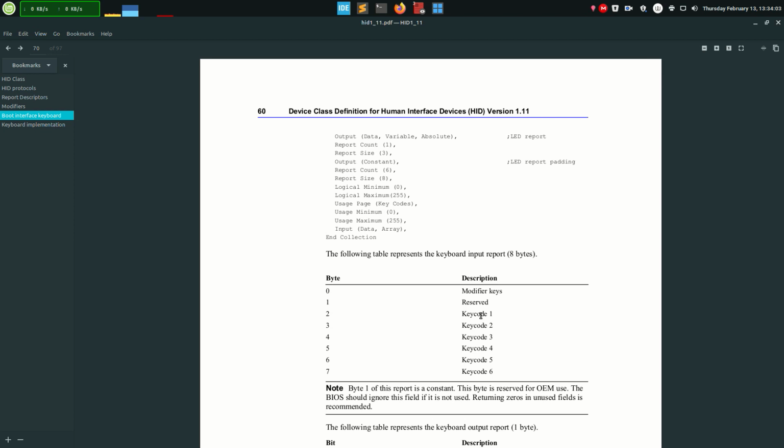The next thing is also the USB settings for our HID, the settings for the computer, and this is the first setting the computer gets from the device, so it knows what type of device it is, what driver to get, what the power recommendation is, what the standard is. Like in our case, we're gonna be using USB 1.0 full speed and stuff like that. So we're gonna have to check out those two things.